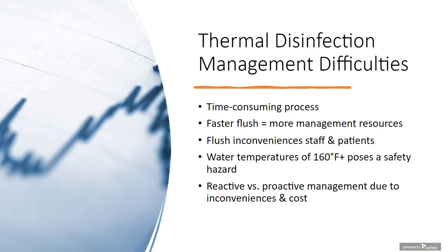So, some of the implementation challenges. The management difficulties of thermal disinfection: it is, again, a time-consuming process. The faster we try to flush the system, the more management resources it's going to consume. You can imagine trying to thermal disinfect a whole domestic hot water system that may have 50 to 100 risers in it. There's going to be a lot of resources that need to be available to make sure that the patients and the staff are safe, because you're going to be flushing 160-degree water down through the fixtures.